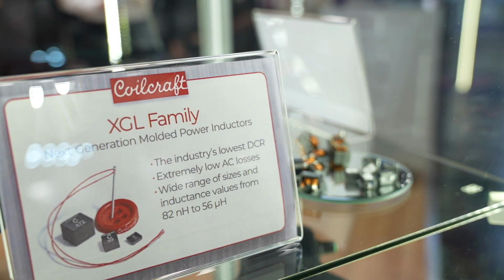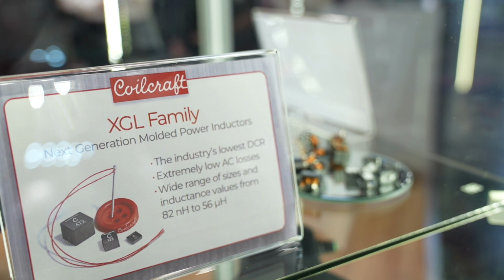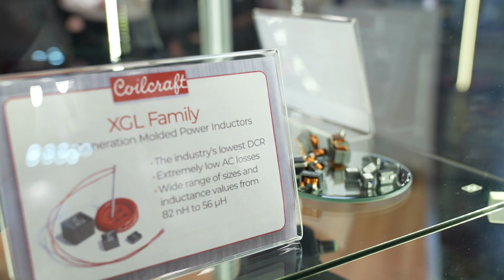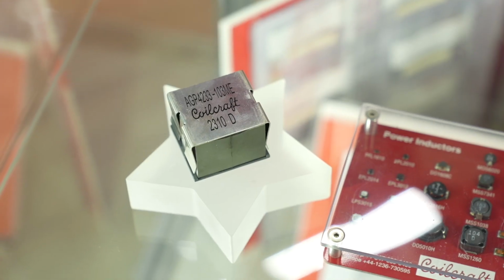In fact, those same inductors have another feature because they're essentially made of core material, some sort of iron or some sort of conductive material. It means they dissipate heat better than traditional inductors. It's much more predictable, much more consistent, and in fact lower. They run cooler, which again helps when we're putting everything very close together. So some simple features that the user might not be aware of are really giving multiple benefits in the end solution.